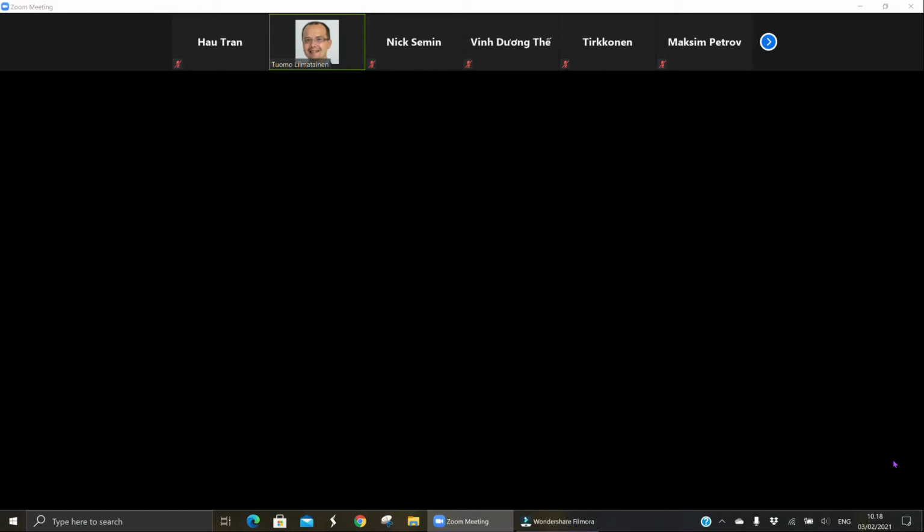And that actually happened in my previous career. We had a large electric motor which had a stator inside. The stator is the iron core of the motor, and the stator was attached to the frame of the machine with an interference fit joint, and the interference was quite heavy. It was sufficient to carry all the short circuit load of the electric motor, something like 50,000 Newton meters.